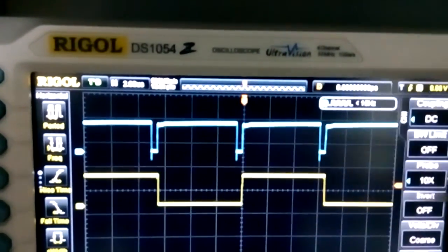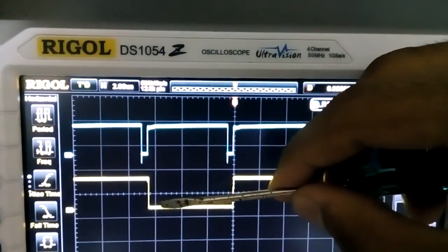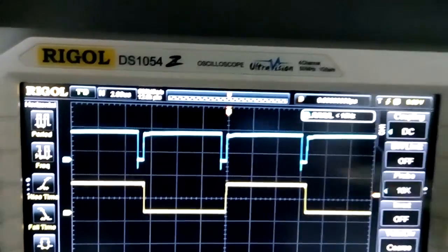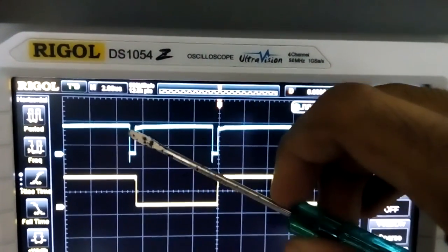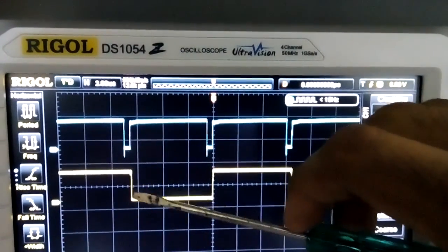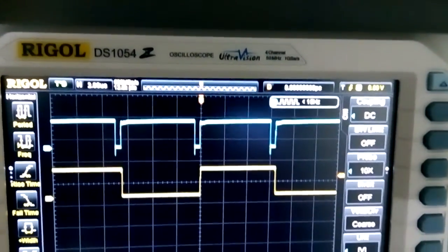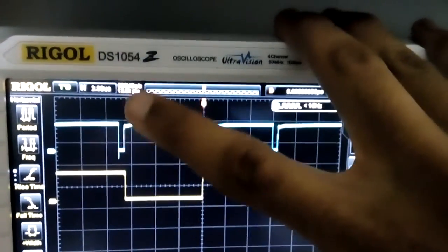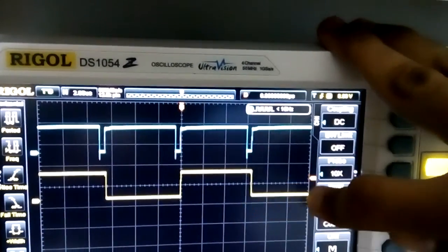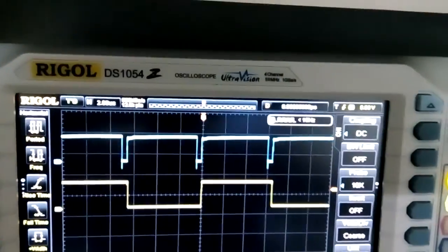I'll just zoom in a bit. Okay, I can't. As soon as this thing goes low, the output goes low. When this thing goes low again, the output goes high, and so on. So you can see 2 complete periods here, from this falling edge to this falling edge, and from this falling edge to this falling edge has been turned into one complete period. And that's because a flip-flop doesn't need a continuous input to maintain its output. You just pulse it once, goes low, pulse it again, goes high, something like that. You don't need to keep its input low to keep the output low. So